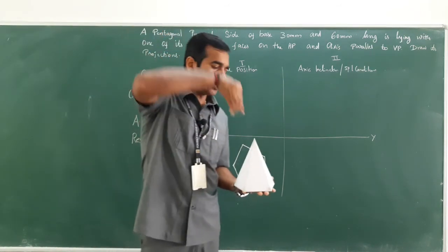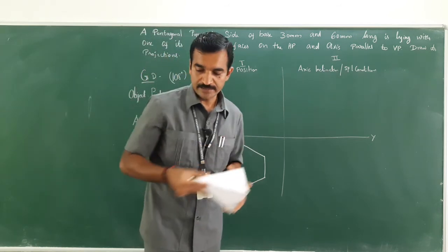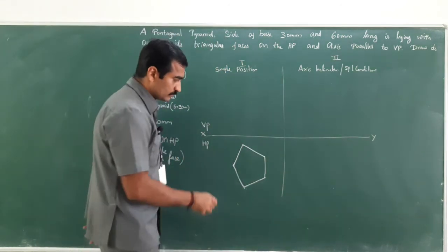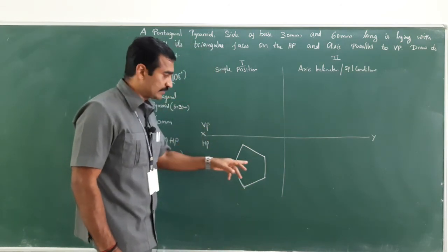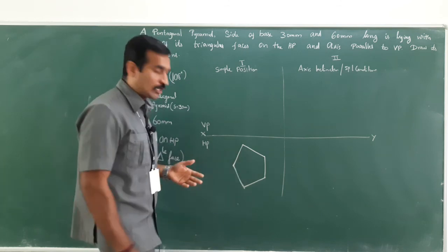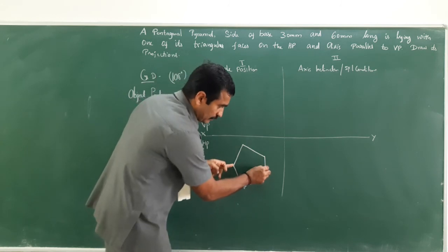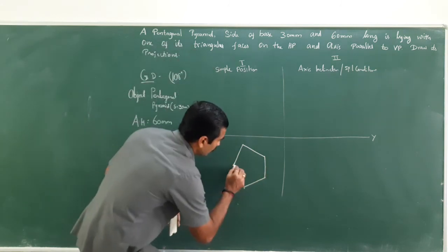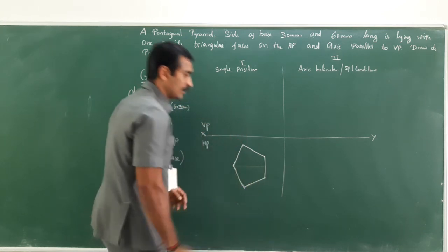So when I look at from the top, I could see the apex or the vertex in the top view. So for which I need to draw the axis, that means I need to find the center, that is the axis. So how that can be drawn? So this is the corner, opposite side center, mark it and draw a thin line, right?